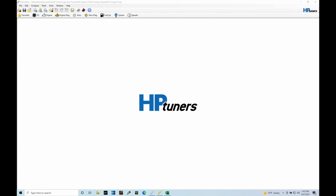The first thing that we need to do is open up the calibration file that I have open here so you can follow along. This is going to be found in our SD tuning tutorial folder in our training course. The file that I have open here is SD tuning number 1. This is based around a 2018 Subaru STI file, and I've converted this over to speed density. Let's go here and take a look.